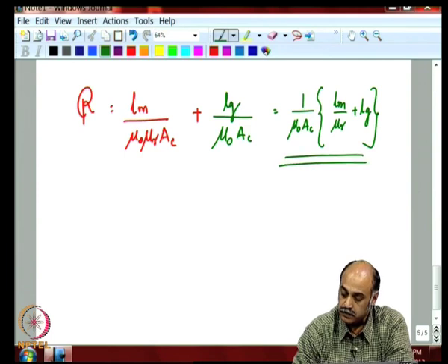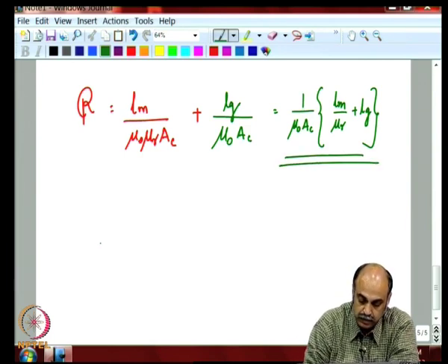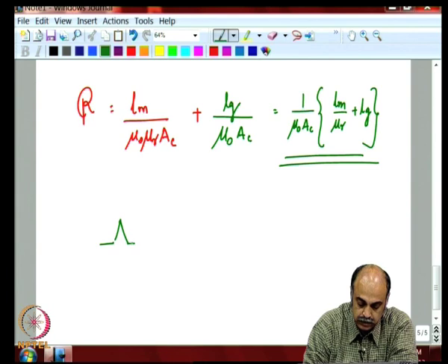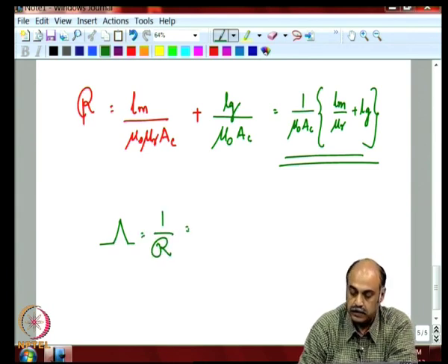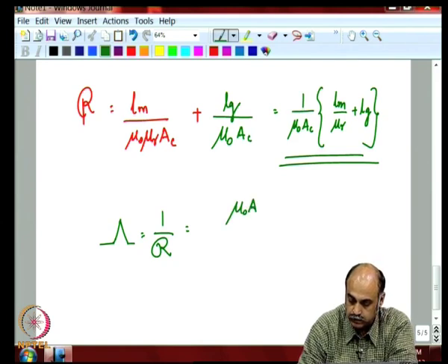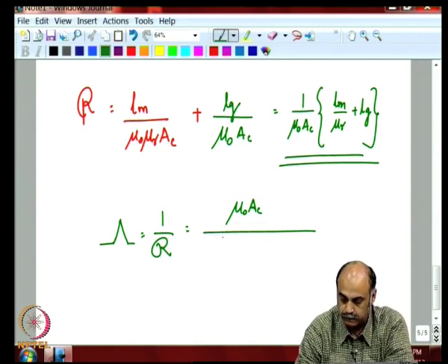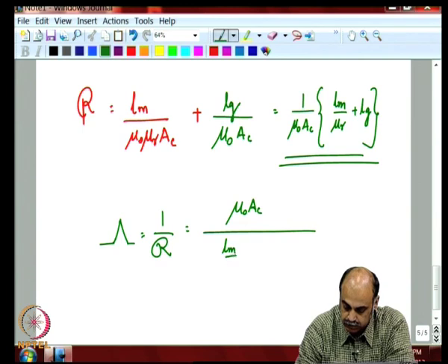So, this is the reluctance, and what is the permeance? Permeance is nothing but 1 by reluctance, and that is given by mu naught AC by Lm by mu r plus Lg.